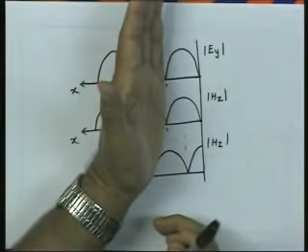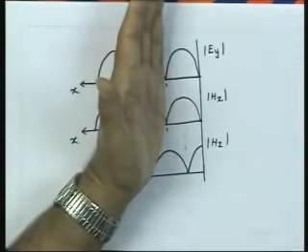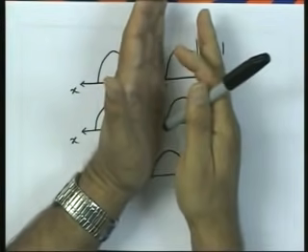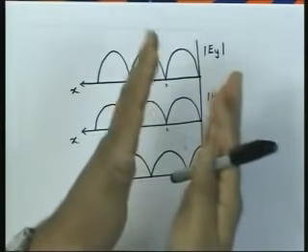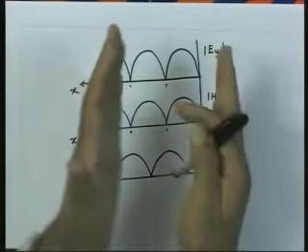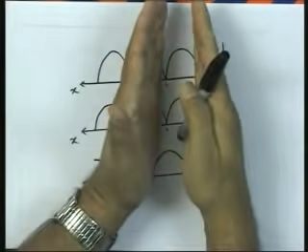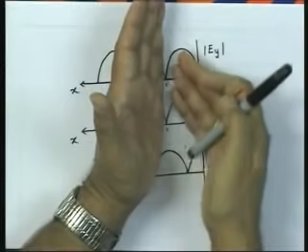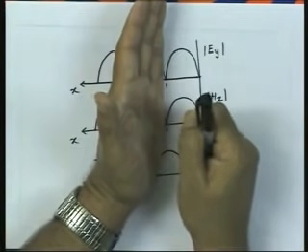However, by inserting a boundary at this distance, essentially now the wave is trapped between these two boundaries. So, I have created a more closed structure, it is no more a semi infinite medium. Now, it has become a bound medium in the x direction. So, this was one interface, this is another interface, and now the field is trapped between these two boundaries.